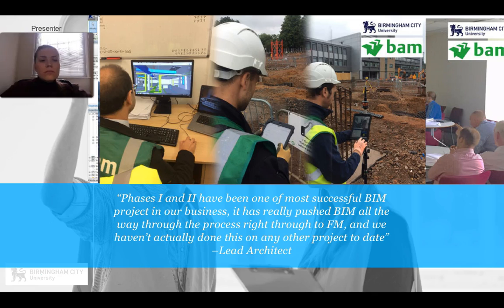Access to the model could be gained via desktop PCs and laptops. Because they were on a network-based system, they were also accessible via mobile applications, and this became very important, certainly at the site set-out stages. One example of a useful tool that was used was the Autodesk Point Layout. The Point Layout software enabled them to integrate real-time coordinates, so GIS data, and input that directly into the model, so that all of the works could be better and more accurately reflected in the as-built BIM.